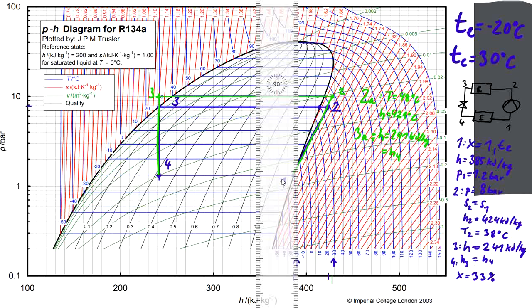So it would come at 25 degrees C. You would have 5 degrees C temperature difference, so at this point the minimum temperature difference is satisfied. And then, as the condensation takes place at 40 degrees C, so at the nearly outlet, the cooling air could heat up to 35. So you would have a much lower mass flow rate of the cooling air than in the first case. But now let's run the numbers and get the actual values.